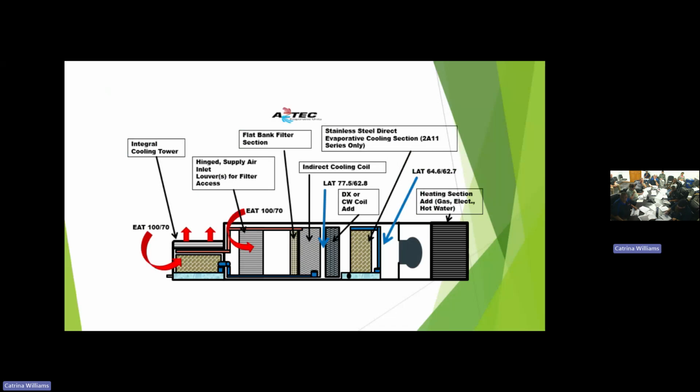We've got, I think it's a 5-story office building out in Denver with one of these units on it. Last I ever heard, it did a great job, pulled the whole building down, and again, no refrigeration. But that's a big unit. I think it was 20 tons operating weight. And that was a complete system, heat and everything. So they can be used in office buildings.